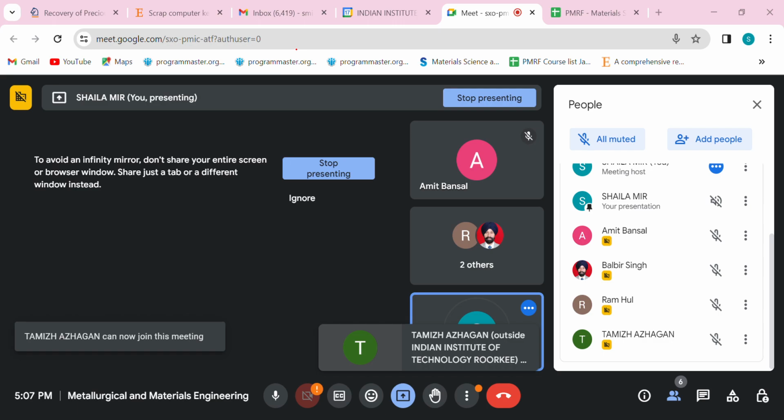So then we have another question which says that an indenter used in Rockwell hardness has the following geometry and material. So yes, we said that we have two types of indenters in the Rockwell. One is Brale indenter and one is a steel ball indenter. So the geometry listed first is square base diamond pyramid with 136 degree included angle. This is not true because this was for Vickers hardness.